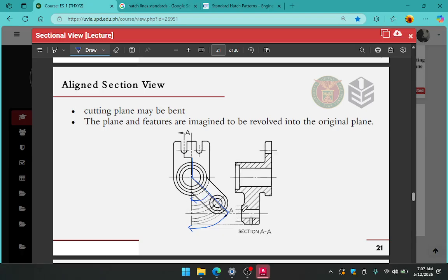Okay? Because if we just do a normal projection, say like that, the object should end here, and the center of the object should be somewhere here. Right? Because that is its normal or orthogonal projection. And this can be done; AutoCAD also allows for this normal projection. But the bad thing about this is that our views here are shortened, because it is no longer showing the correct size of the object.